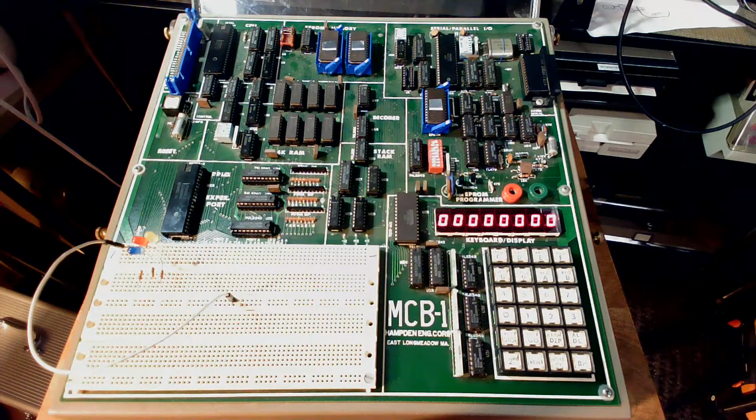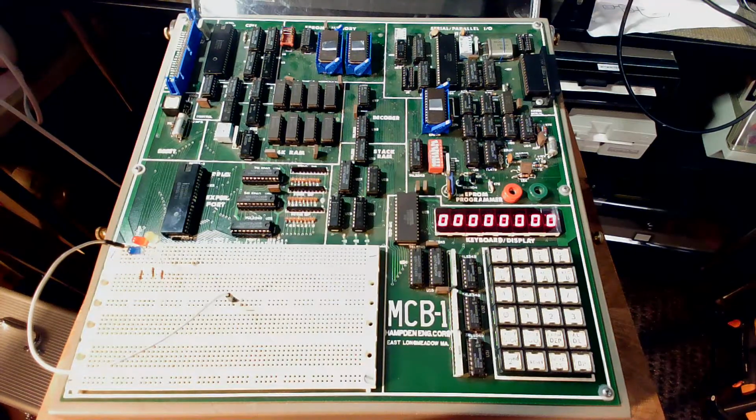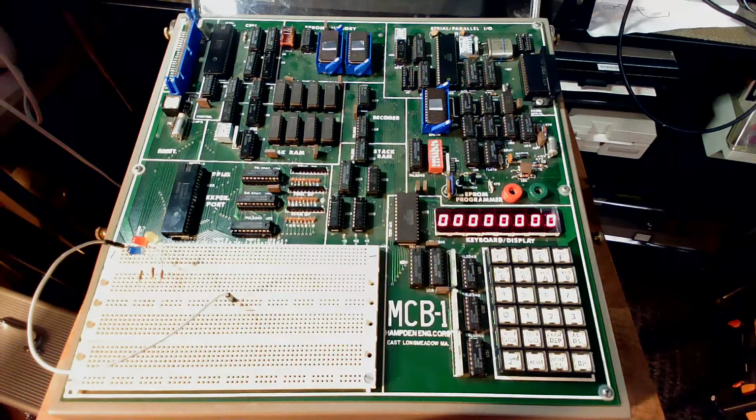So at first it wouldn't work at all, and the reason was that I needed to put the 8085 into a certain masked interrupt mode first for the keyboard to be read and processed properly. But yeah, that got sorted out, and it's actually a very nice system, I must say. I'm happy I got it running and that I understand now how to program it.